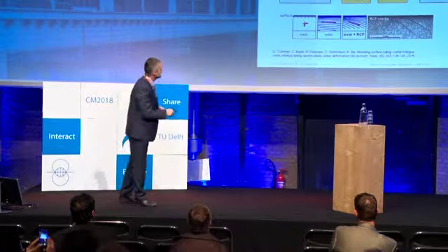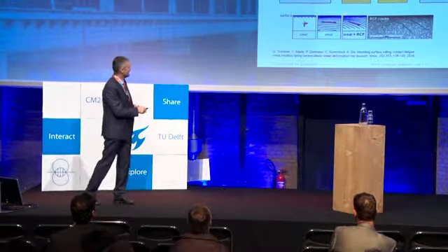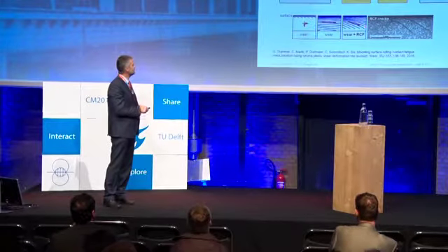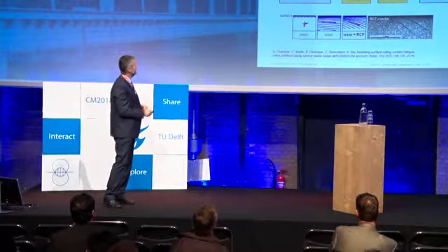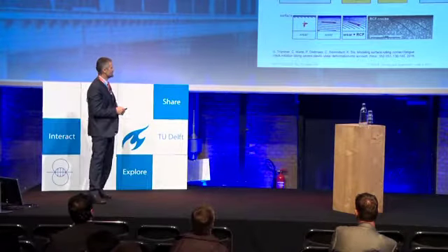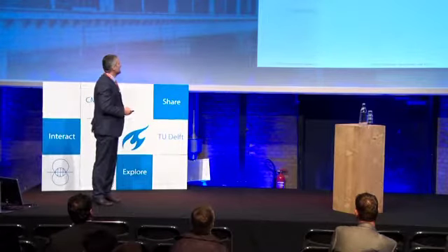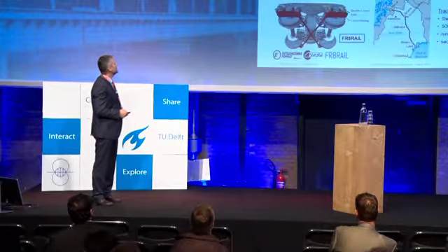And the third case is the interesting one, the wear and RCF case, where the cracks again have a preferred crack growth direction. They grow along the surface, they grow very fast away from the surface, and cause macroscopic RCF cracks. So let me come now to the application of the methodology.